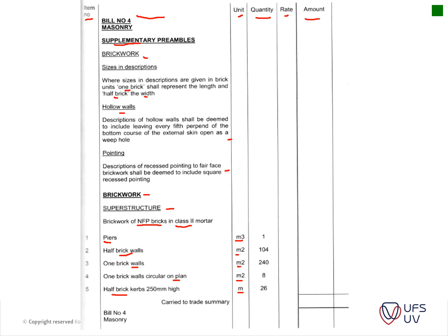So the main thing is you want to have a combination of information. For instance, here they included the height, so the contractor knows how high it is, and then he's given a length. So he can easily calculate how many layers of bricks he needs for this length of construction. The main thing is the contractor should have a complete picture of how he's going to measure or price, and what he should allow for this item.